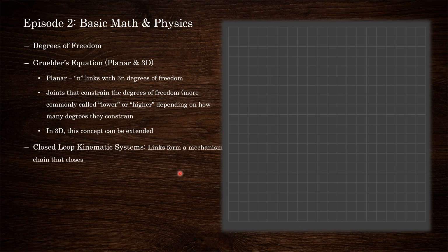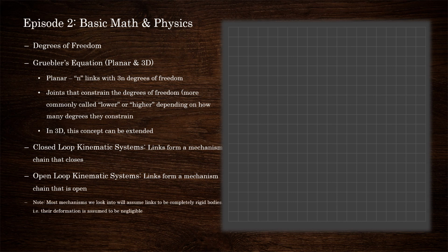So we will study a little more about closed loop kinematic chains. So what we saw here was open, but what if the last link is actually joining with the ground? What is required to define it? That's something that we'll learn. We learn about open loop kinematic chains. What we saw here was essentially an open loop one. Serial robotic arms, even in 3D, till they touch an object in the ground, are essentially open loops. The moment it touches, it can be defined differently. So it's something that we will learn as well.